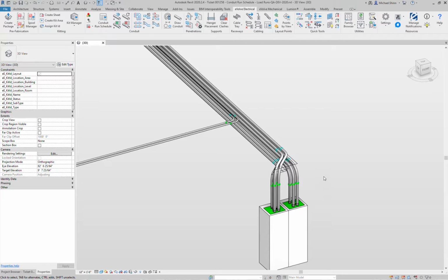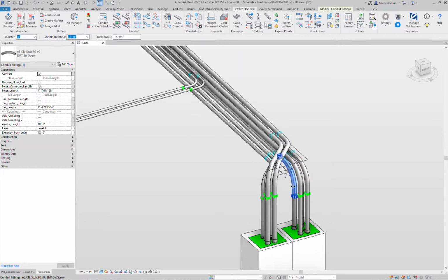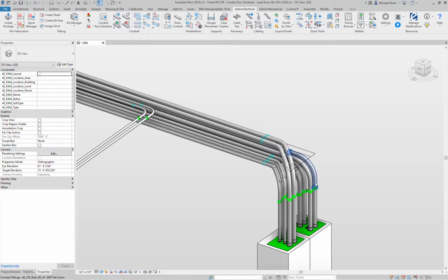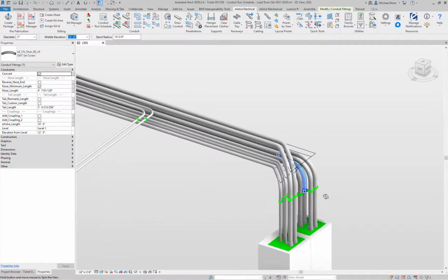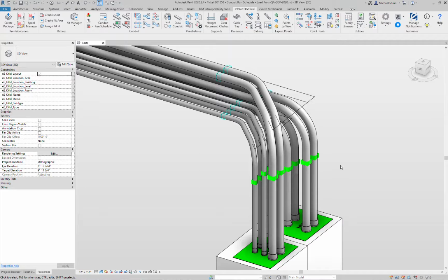This is when the fun part of this presentation begins. So this is our starting point for our model. We've got a couple kick 90s here, and we've got a couple stub 90s. What I want to do now is optimize this section and turn these all into full 10-foot sticks, so that I can then push this data out to the prefab shop.